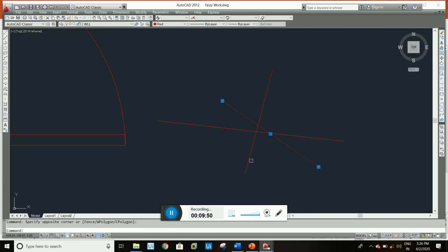Now, guys, this comes back to the previous state. So it is exploding the object: this is one block, and we explode it and convert it into small pieces or small lines. We just select this one, press X on the keyboard and enter. Now see, this is a separate part, this is a separate part, this is a separate part, and this is a separate part. This part is rectangular, and we can also explode this one. Now see, this is one line, the others are separate. So explode is like breaking the object into small pieces.